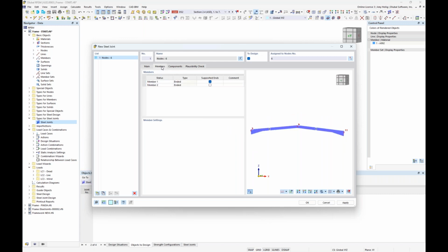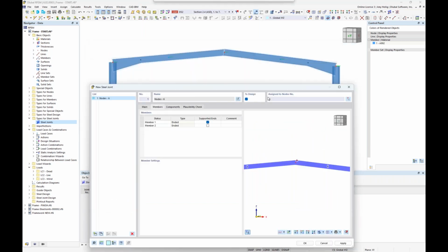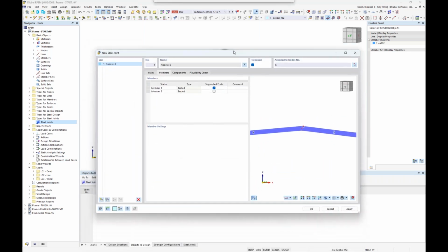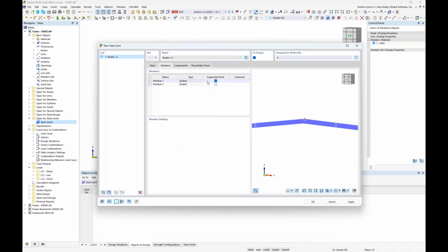Looking at this second tab. So remember that we are going to more or less extract out this submodel for our connection design and run it completely separate from our steel frame that's happening here in RFEM. And because of this, we need to fully support one of these members in that submodel. So we'll go ahead and utilize the support for the beam over on the left.